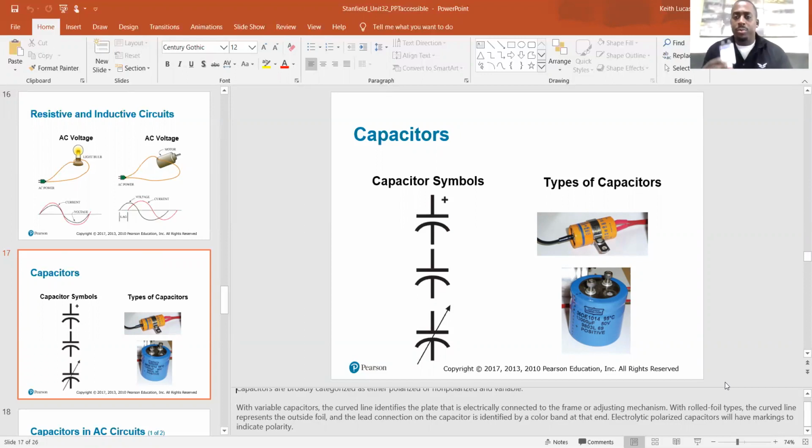So this is the typical run capacitor that you'll see in an AC system. And this one happens to be a bad one. I could tell by looking at it, because if you look closely, this top surface is convexed. It's kind of bubbled out. So when you see that, you know that it's a bad capacitor.